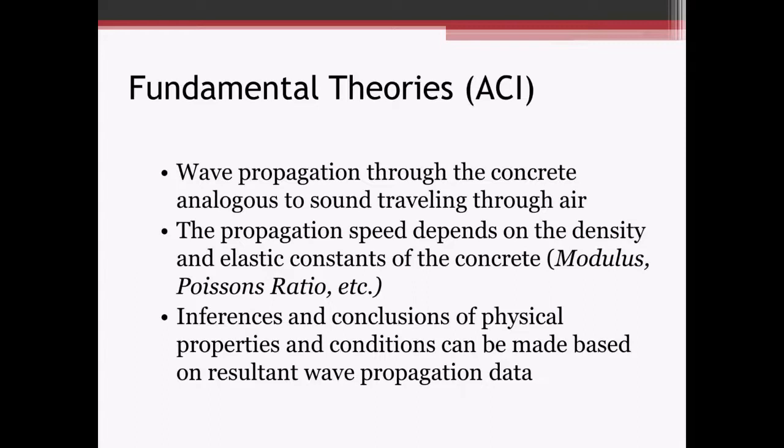But that's the fundamental theory. The wave is traveling through the concrete, similar to traveling through air, and bouncing off all those different edge conditions. How that wave travels through the concrete is very dependent on the density and the elastic properties of the concrete. So that's where we're getting our quantitative or qualitative information: based on how those waves are traveling through the concrete and reflecting, and what kind of information we're getting back. And then we make some conclusions based on the properties.